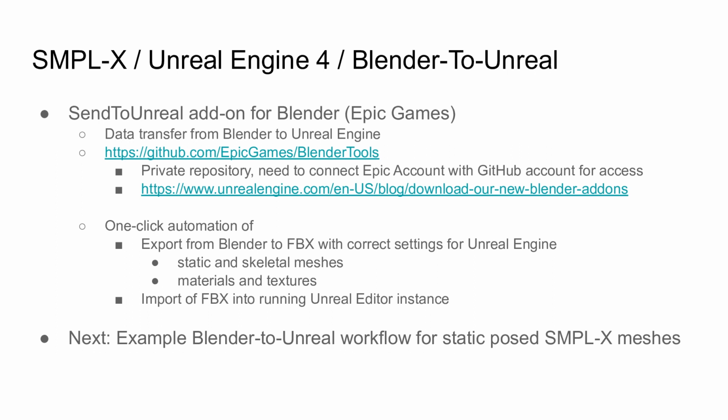Now we're going to show you how you can get data from Blender into Unreal Engine. For this, we'll be using the free Send to Unreal add-on for Blender, which was published by Epic Games, the company behind Unreal Engine. The main job of the add-on is to make it easier for you to transfer data between Blender and Unreal Engine. It's available for free on the Epic Games GitHub repo. Please remember that it's a private repository, so you first need to connect your Epic account with GitHub to be able to access it.